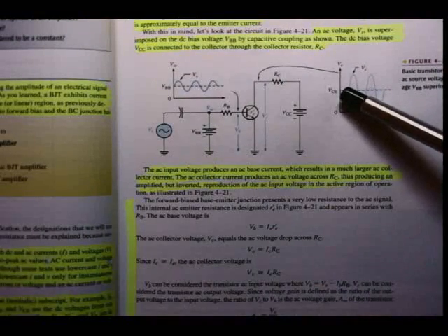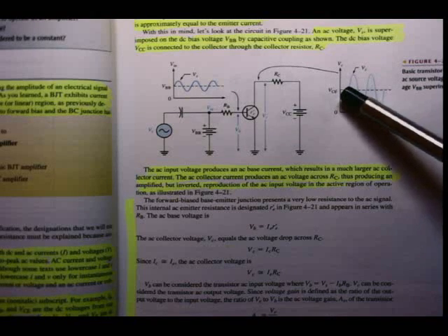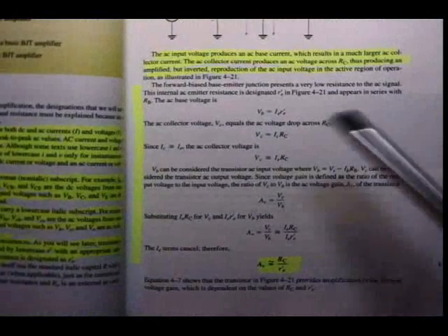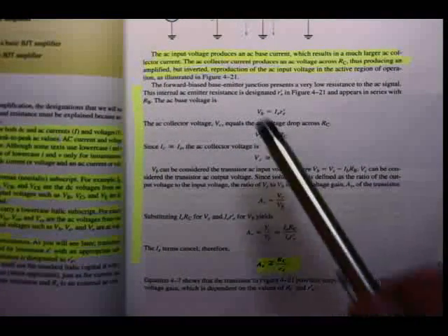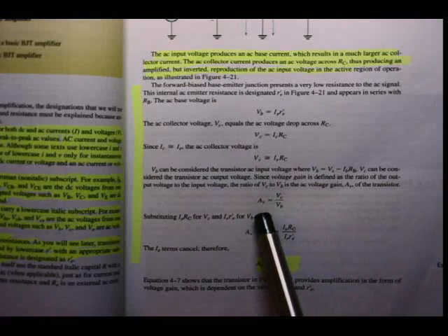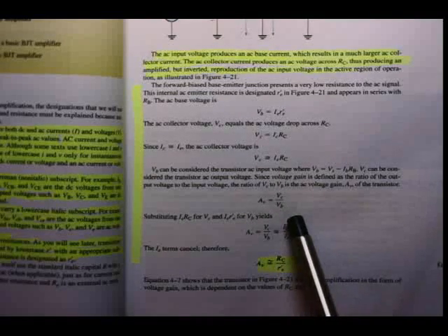Now there's VCE. Alright, so to get this ratio, the voltage gain is a ratio. It will be the output divided by the input, which is VC over VB. That's why if you look at the formulas here, I want to determine VB and I want to determine VC. So in the end, the voltage gain is VC divided by VB.